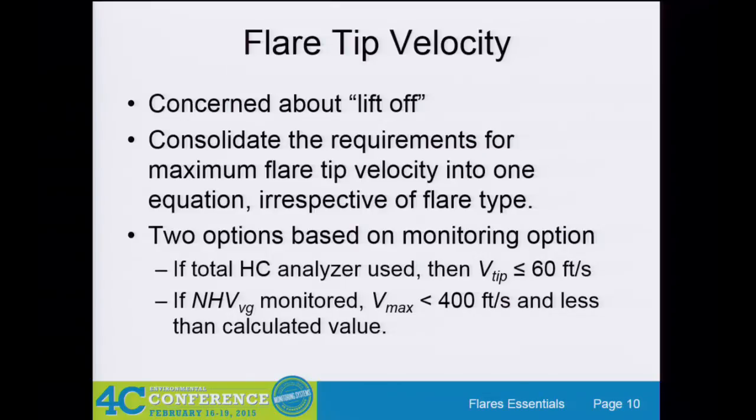They took away, because again, they're going to decouple this part from 63.11, all the equations that you can use in 63.11 and the different flare types and how those all have different requirements. They're removing that tie back. So now they said, well, you know what? We're going to pull all these equations into one equation because we say that really it doesn't make that much difference. So we're going to have one equation for all the different flare tip velocities.